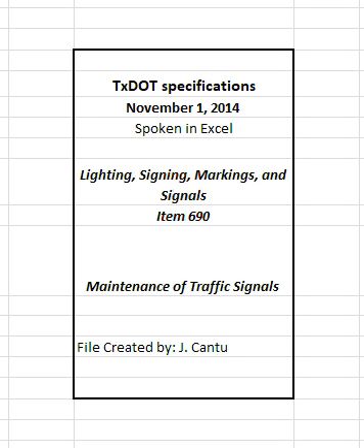4.3 Concrete. Install concrete in accordance with Item 421, hydraulic cement concrete. 4.4 Ground boxes. Install, repair, replace, remove, or modify ground boxes in accordance with Item 624, ground boxes, as shown on the plans, or as directed.